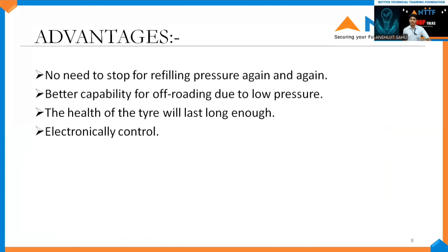The advantages of the self-inflating tire: no need to stop for refilling pressure again and again. For most off-roading, we need different pressures on different terrain. If you are rock climbing, the pressure should be less. If you are going through mud, the pressure should be more, because mud is very soft soil, so we need more traction to get forward. We don't need to come outside and deflate and inflate again and again, because we have a control unit inside the dashboard.